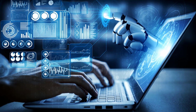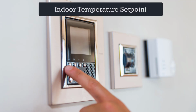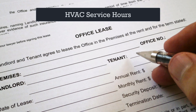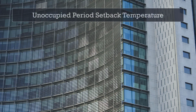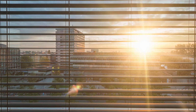The Optimum Start solution should emphasize three basic criteria: desired indoor temperature set point when cooling and when heating. They should be different values for each operation. The building's occupied period begin time, otherwise defined in the landlord-tenant lease as the time HVAC service begins during weekday business hours, and building indoor temperature recovery time, verified by monitoring indoor temperatures prior to and at the occupied period begin time. Unoccupied period setback temperatures and other energy conservation measures, such as exterior shading and closing perimeter blinds, will impact building indoor temperature recovery time.